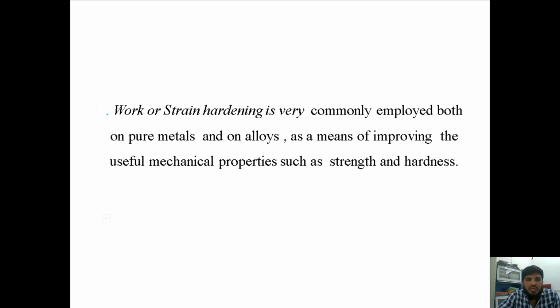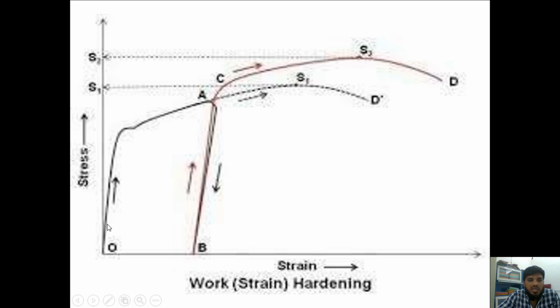When loaded, that is, when we give a load to the workpiece, the strain energy increases. Strain means nothing but the deformation with the stress. So when you apply the load, there will be a strain, a deformation produced, which I will show you in the graph. If you see this graph, if I am applying the stress, in the initial condition, which is called the elastic condition, if you remove the stress, the material will regain its original nature.